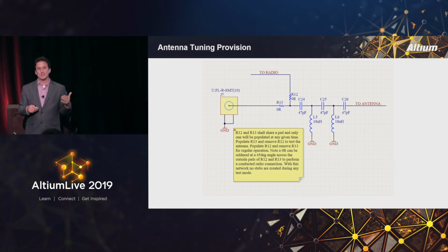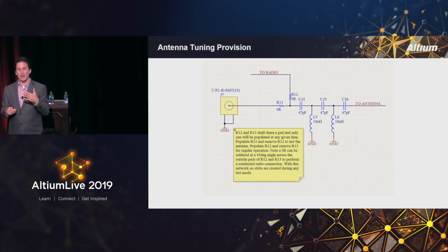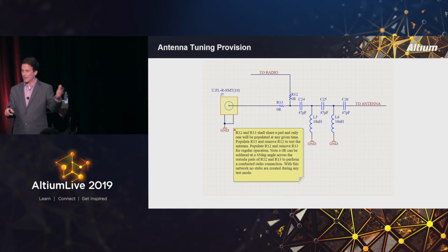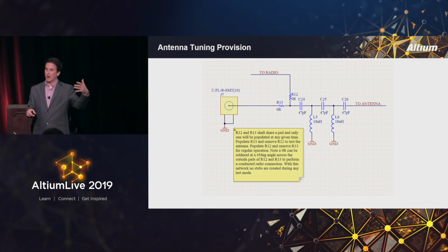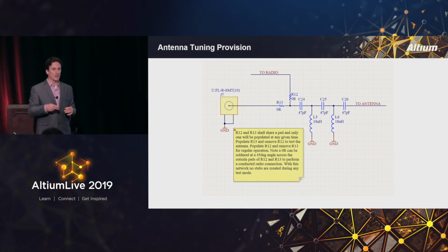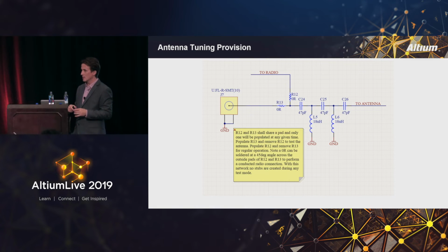And you do this, and characterizing your antenna will be incredibly easier. We tune our antenna for the input impedance into our antenna, the output impedance of our transceiver. And then we take this thing and we put it into a case, and everything about that case changes the antenna.